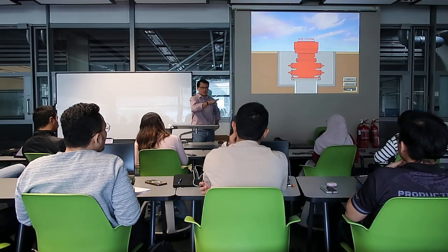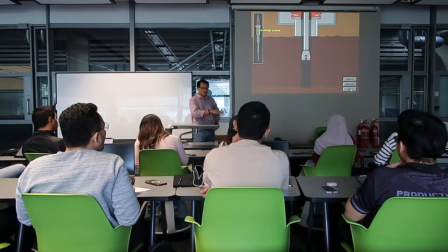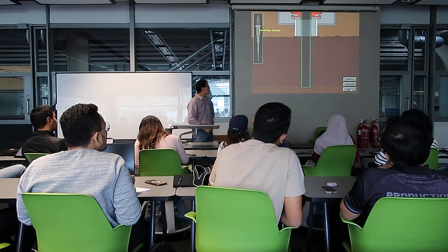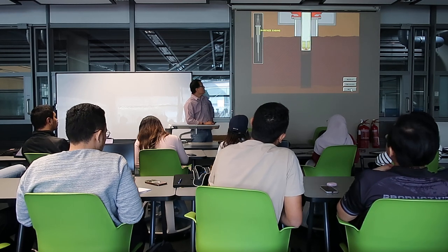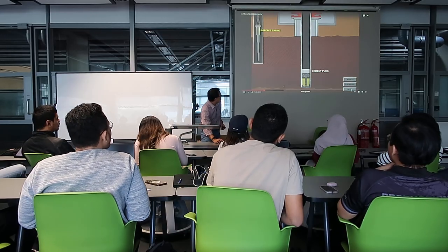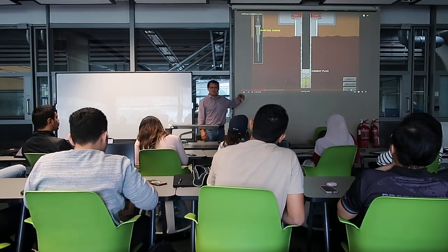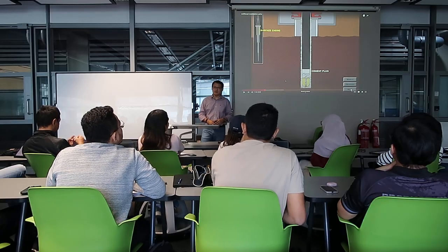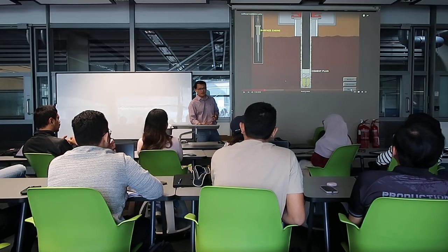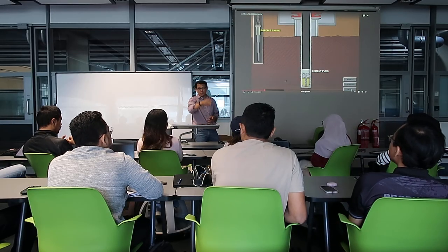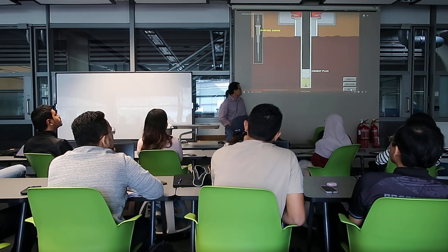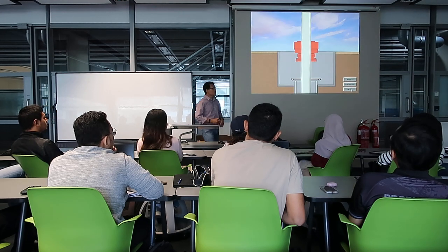That's how we drill with the diverter for the surface casing section. So we run the drill bit, drill the surface casing section, then we run the casing. When we do the cement, I think you have all attended this already, right? So you guys know the cementing, right? The casing bottom has a float, so it's a lot easier. You push out all the cement, so the cement is supposed to go up. At this stage, all of it will be outside of the casing.